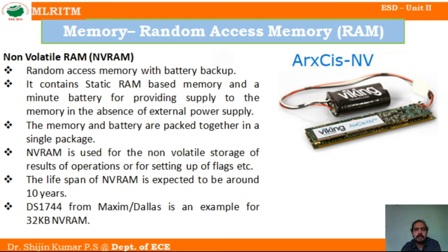It can be a static RAM connected with a battery. Why are we not using dynamic RAM? Because dynamic RAM needs a refreshing circuit also, so it will consume more battery. That's why we are using a static RAM, and a small battery will be connected to the RAM as shown in the figure. It will provide an external supply, so even if the power is gone, the data will be present inside.